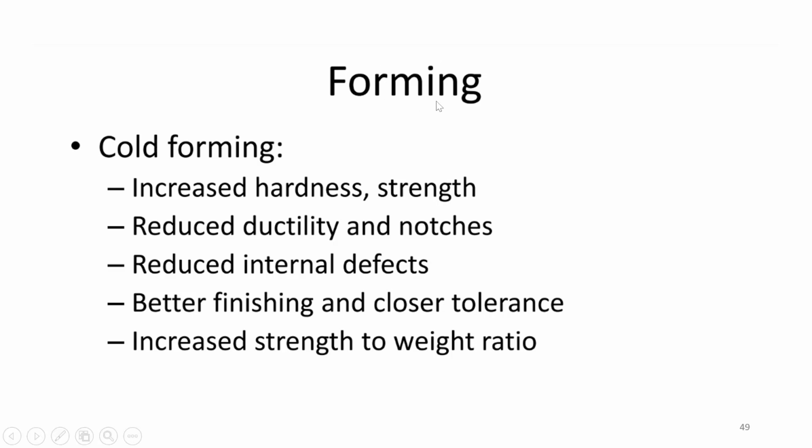Next you have forming processes. In case of cold forming, you will have increased hardness and strength. Cold forming occurs at room temperature. In this case you will also have reduced ductility, and there will be formation of notches. You will have reduced internal defects, better finishing and closer tolerance, and increased strength to weight ratio compared to other processes.